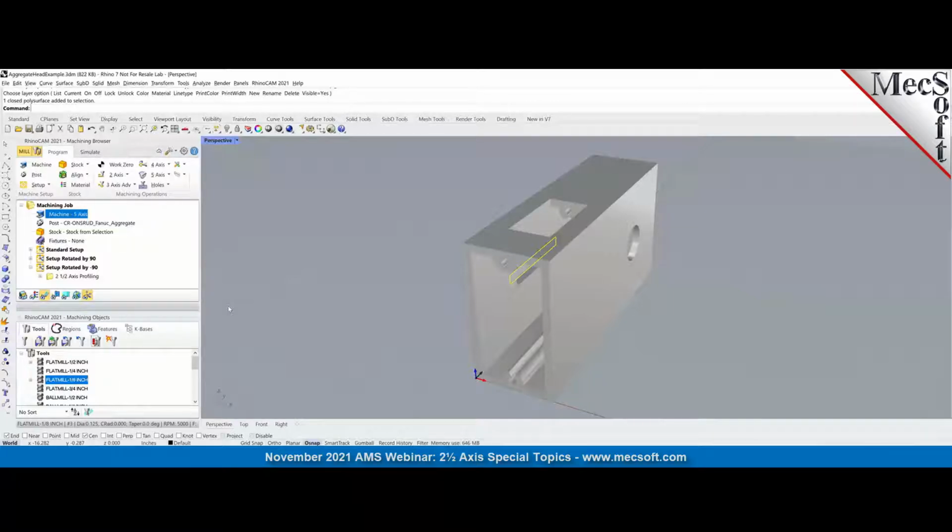What you'd have to do is have the aggregate head without any rotations, so the tool is pointing down, and then you zero it out that way. And then once you zero it that way, and you specify the gauge length in the machine tool, then we will do the transformations using that gauge length.